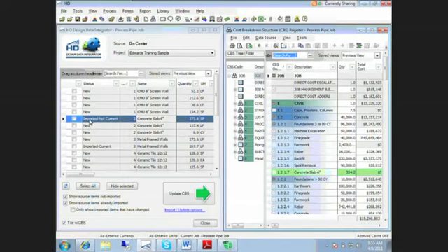Okay, if you look, I've got this item highlighted over on the left. The on-center item is highlighted. What we do to help you find it in the estimate over to the right is we highlight it in green. So there's that concrete slab over in the estimate to the right, highlighted in lovely green. And you can see the quantity that we previously brought into the estimate was 324. Now that we changed that slab over in on center, the new quantity is 373, and that's why it says not current. So we're flagging that for you.